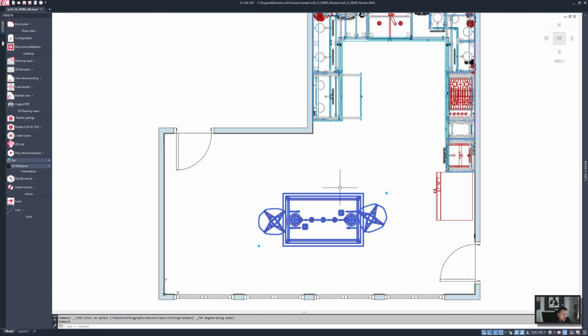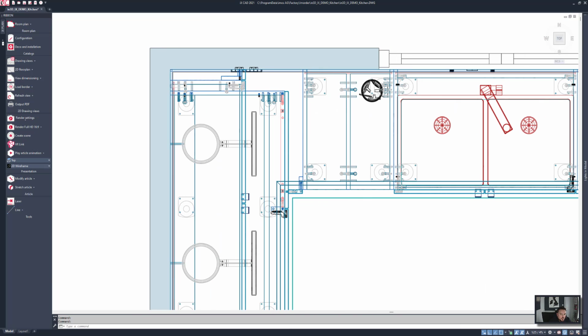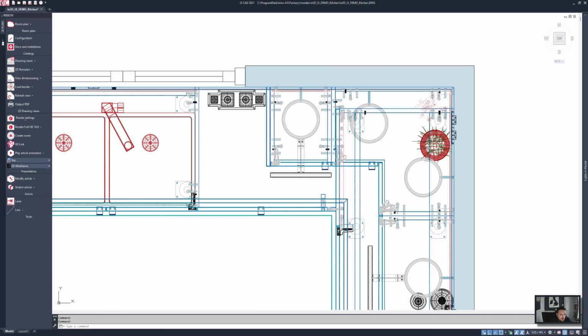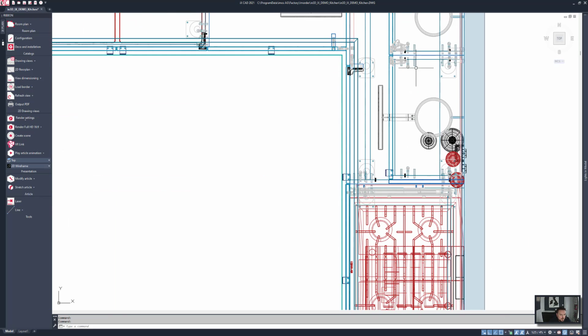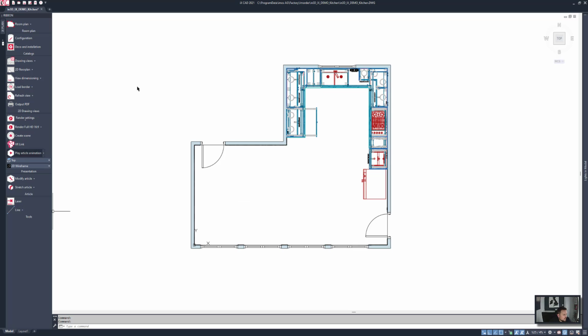And then for the technical drawings, let's get rid of some of this information in here for the decorative items. We don't need those now that we have our renders done. So we'll just delete those out. And then in here now, all I want to do is just click on my drawing views button.